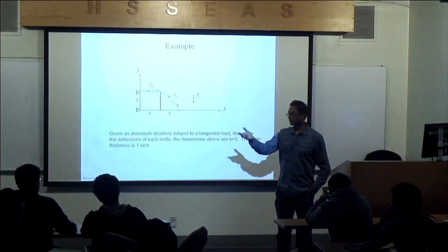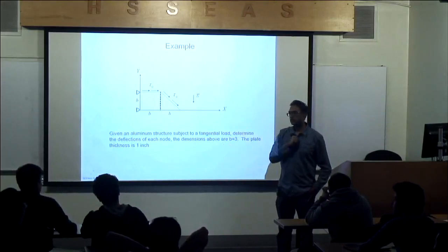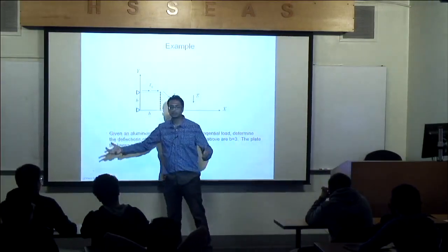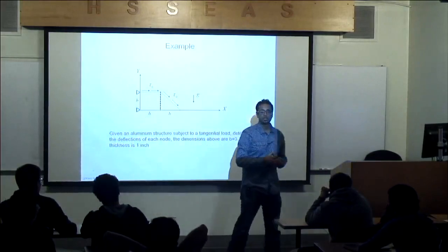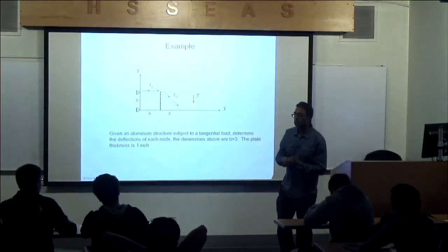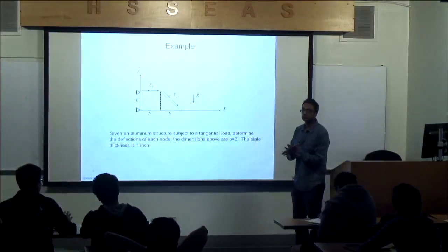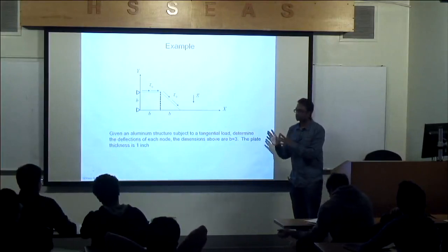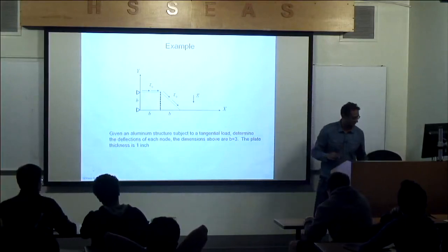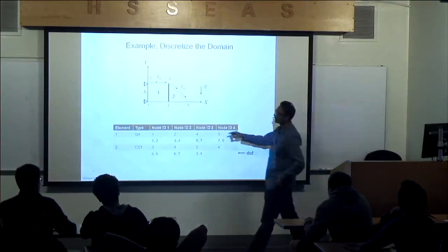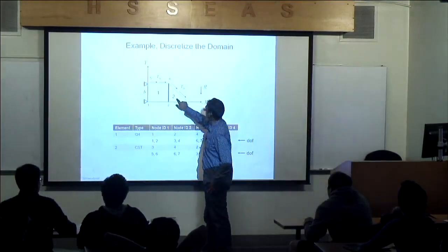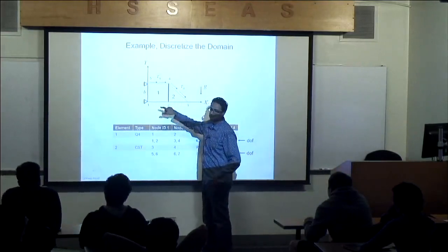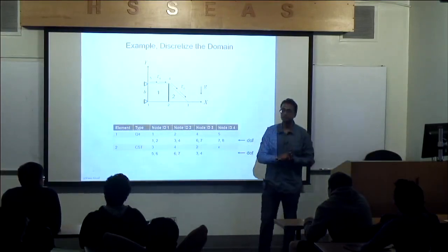And I'll be covering, you had a question about how I tackle tractions, whether they get mapped. I still remember your question. We'll cover that a little bit. All right, you follow the example so far, what we're going to do? So step 1 is to discretize the domain. I don't want to do 20 elements because it's a PowerPoint, so we'll do 2 elements. One element here, a square, and one element here, a triangle, okay? So just 2 elements. I think your homework has many more elements.